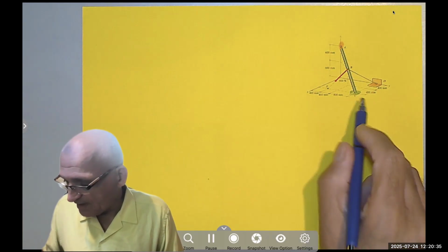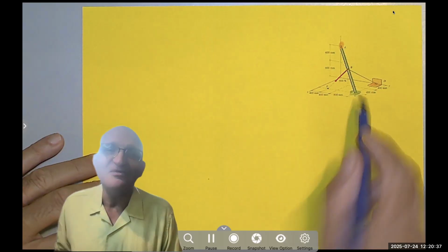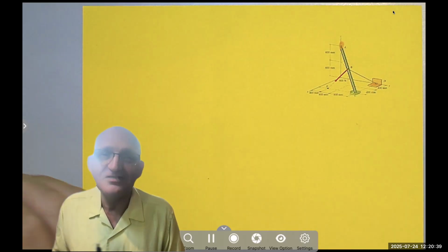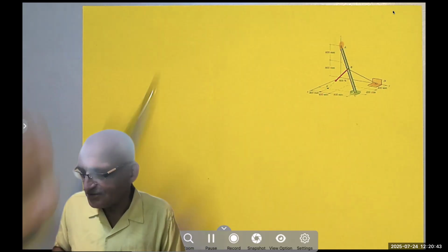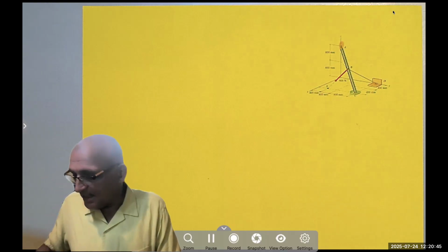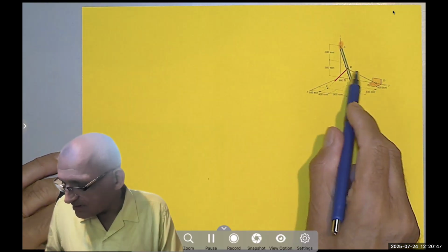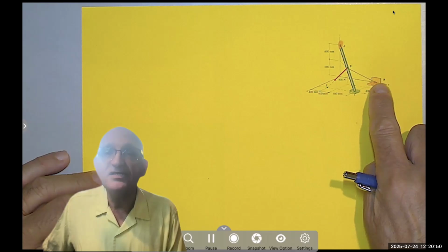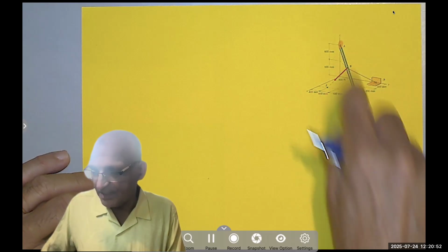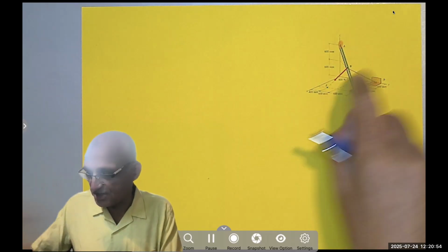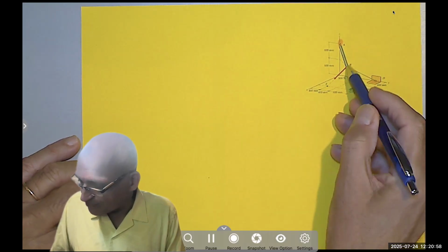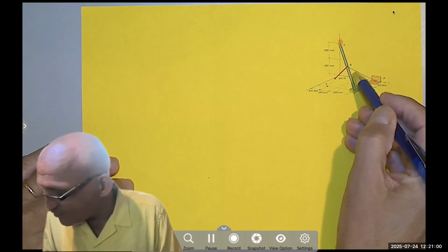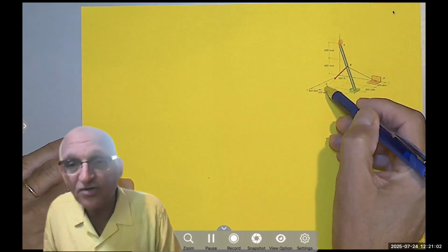support. Here, they spilled some oil, so they are telling you this is a smooth surface, okay? It doesn't prevent motion in any direction. And then we have a cable. Notice I don't care about the support. It's not connected to my rigid body. My rigid body is just that, so it's connected by a tension. And then there is a force of 800 Newton going from point B in the direction of point E.